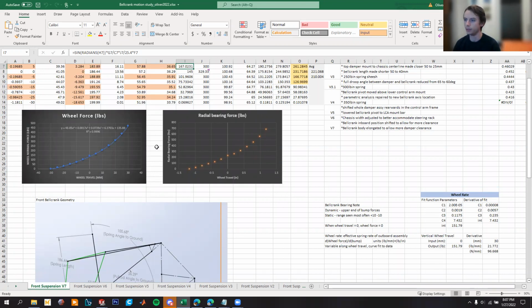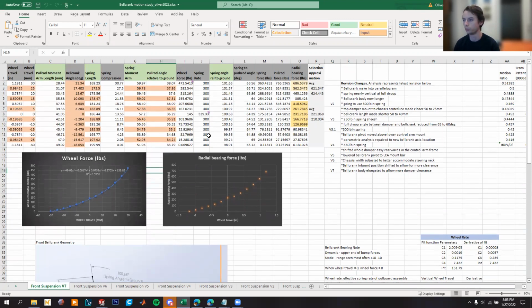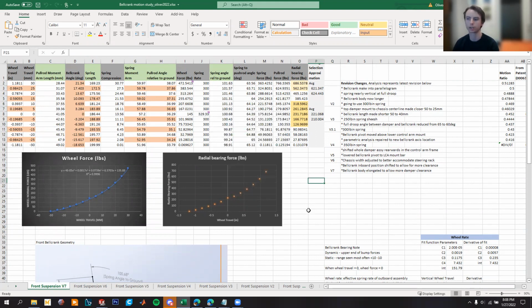That is going to be a reference for once we have a final driving vehicle. There are parameters that we can change, such as the camber angle of the car, or with regards to the wheel force, we can change the spring rate, or we can change spring preload to adjust the suspension characteristics. The dampers that we use, the Öhlins TTX 25s, they also have adjustment on the